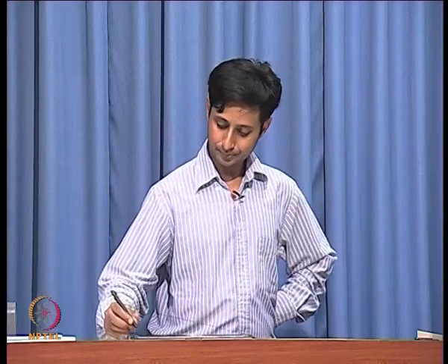So, what you see over here, the method of open circuit time constants, is that you can basically see for yourself which capacitor is contributing how much time constant, which capacitor is responsible for slowing down my system. So, which capacitor over here is the culprit? Why is my 3 dB frequency only 84 megahertz? Why can't I make it 1 gigahertz? Who is responsible?